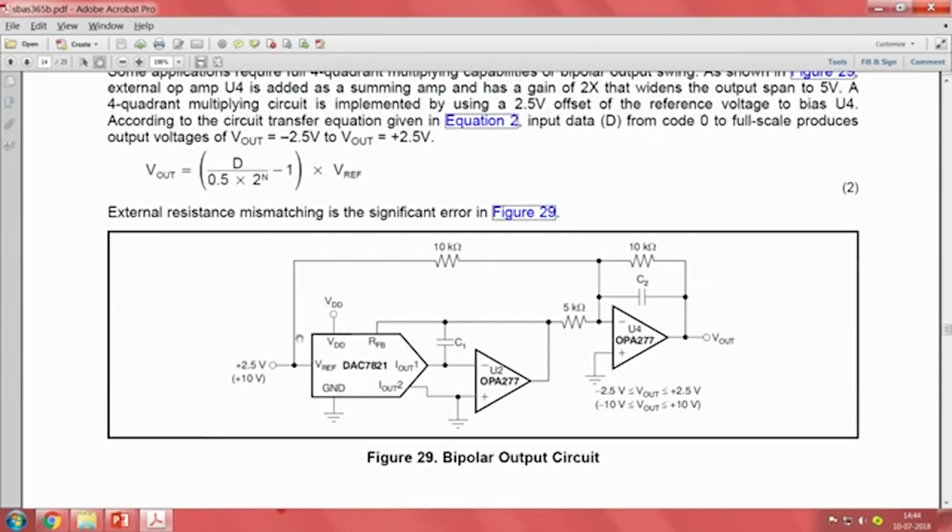One is, if you are confused or stuck as to what exact circuit to use for your typical application, most of the time that typical application will be there in the datasheet, and you can borrow from it and then make minor modifications as you want. Another one is, you will be able to see applications which you never even thought of with that IC. So it forms a part of your learning curve also. So you can learn new circuits.